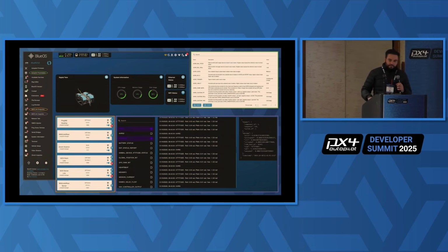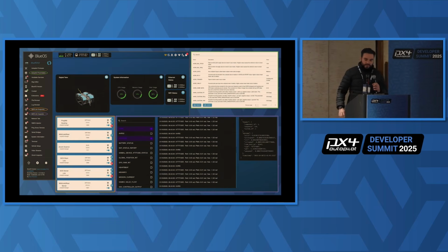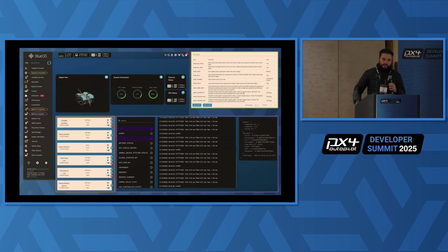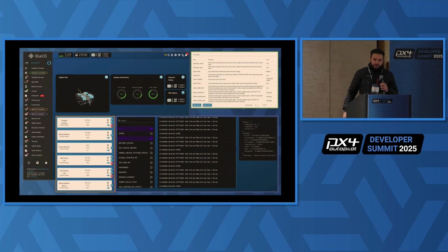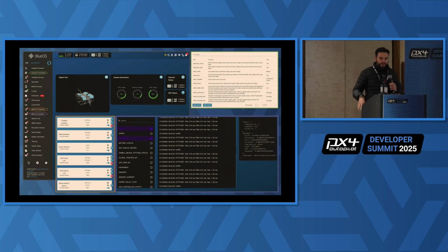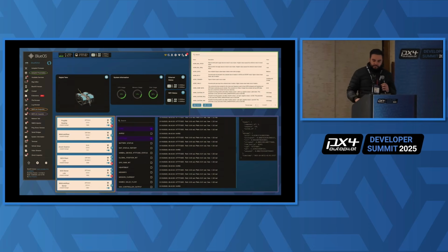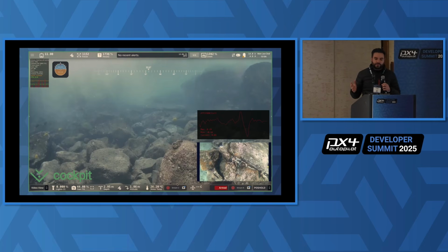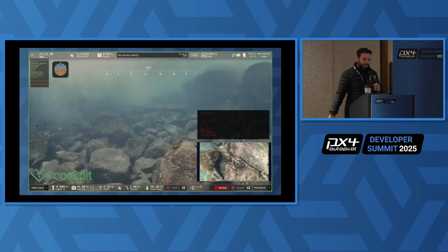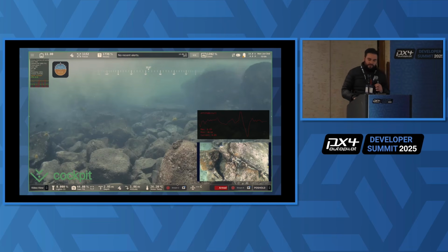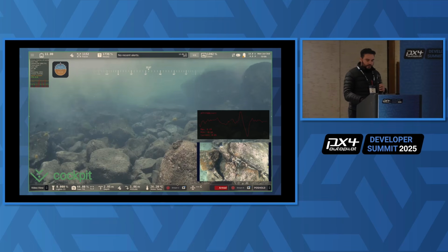So all the data related to the MAVLink information, showing attitude, having a digital twin, investigating MAVLink messages, everything is possible through the REST API and WebSocket. BlueOS was developed entirely over MAVLink to REST. And of course, nothing is holding you as well from developing a ground control station. As an example, Cockpit is an open source web-based ground control station that was developed from the ground up. It uses MAVLink Camera Manager and MAVLink to REST to do all the intercommunication.